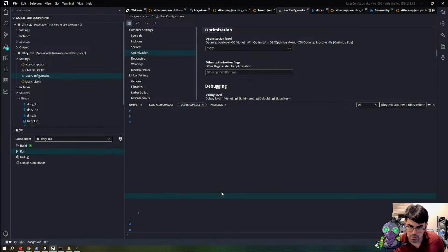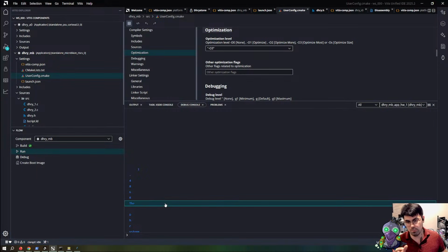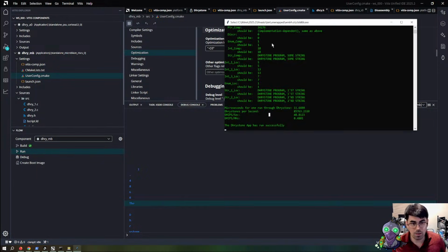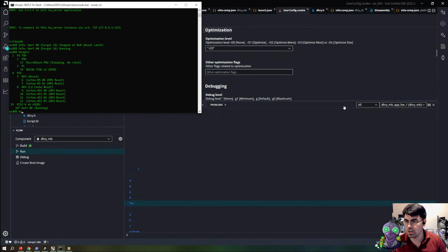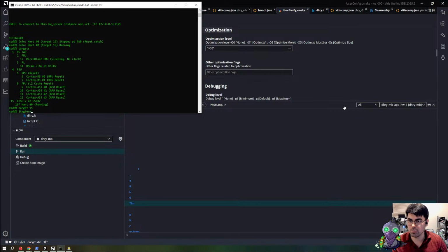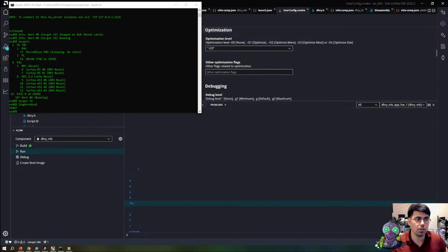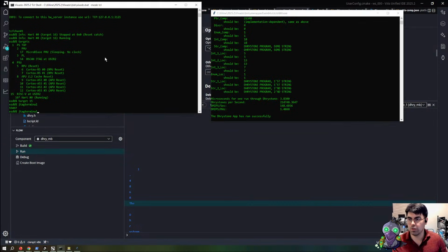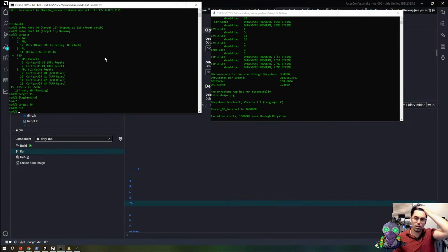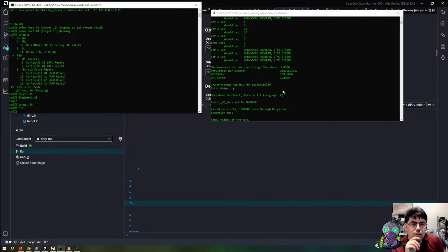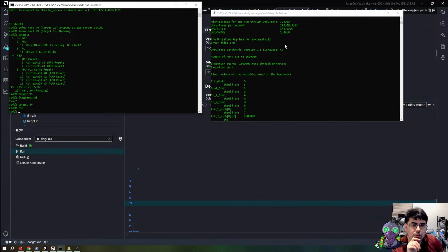Okay. Performance here, the DMIPS per megahertz was 1.4. So we gained almost 1x. We didn't see it here because we have to go through targets. It's now target 15. We'll do a JTAG terminal and bring that over here. Go with target 16 and just do a reset. Now we can see the benchmark. Oh no, was it? It already has 1.48 there. Okay, so it already saw previous results.